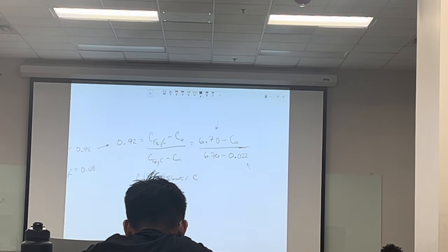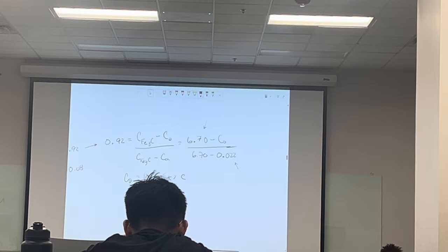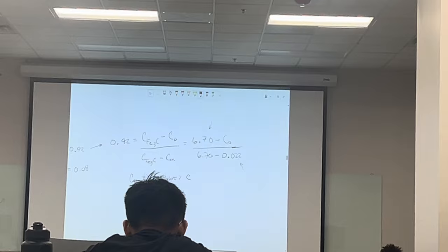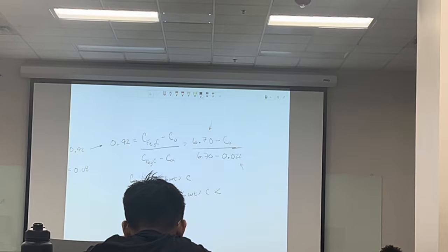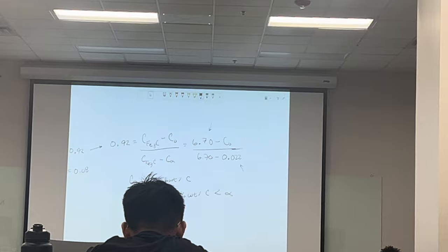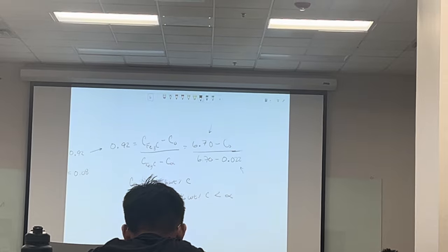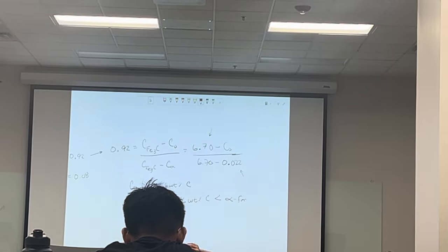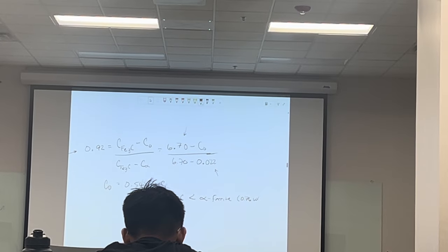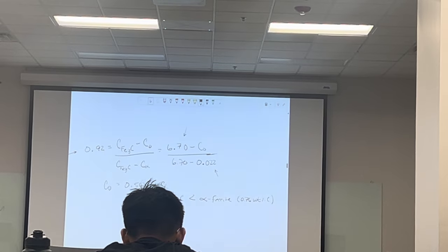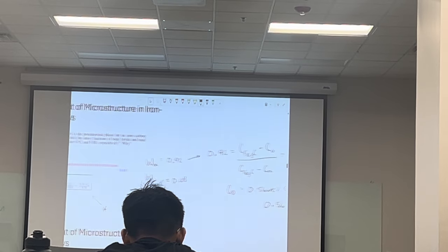So essentially, they're answering that why part at the end of that question. Since this 0.568% carbon is less than 0.76% carbon, that's how we know that it's hypoeutectoid with proeutectoid alpha ferrite.